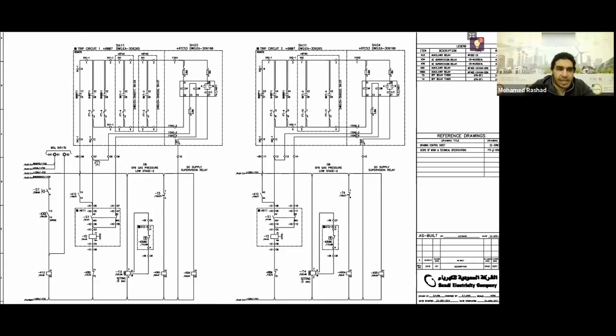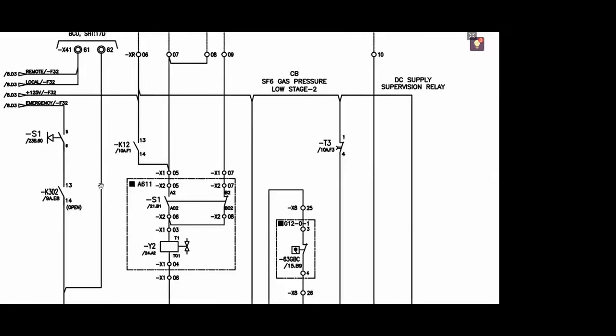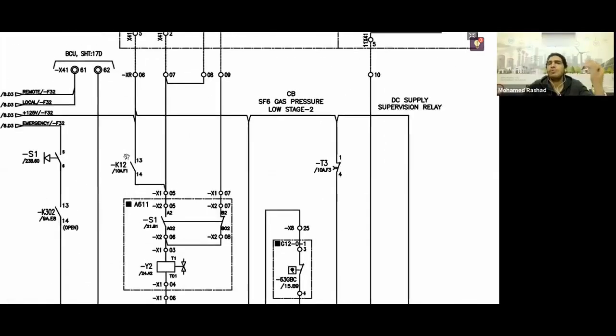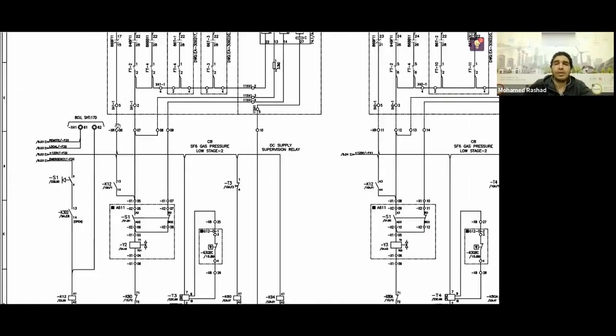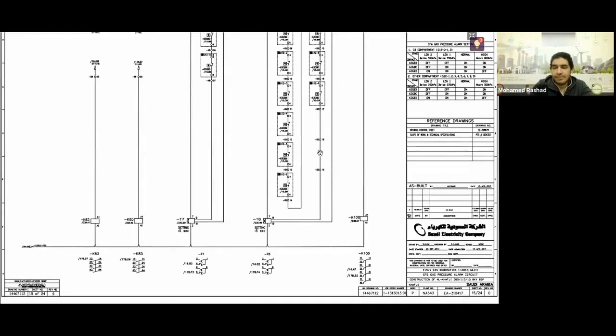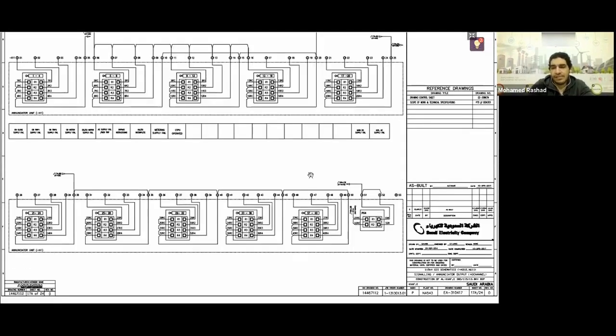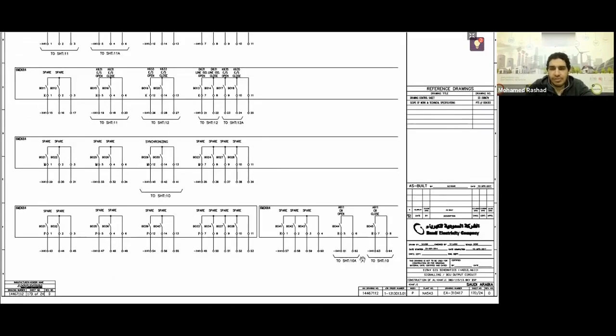Okay, you just want to open the breaker, meaning a normal bridge. When you do it here on the terminal block, it's X41, 60, and 62. This means you have activated the one that opens the breaker, or if you want to bridge it on itself, you'll find it here on page 17. You'll go here to page 17, like this. Here it is. This is 17 ABCD, and this is the one responsible for the circuit breaker.